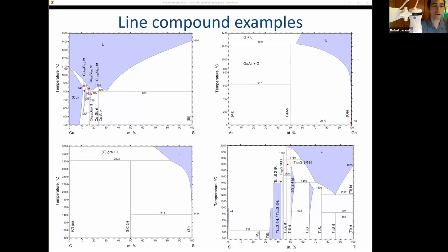Okay, so here's the copper silicon system. You can see that you can get a fair amount of silicon into copper, up to 10%. That's this purple region. There are silicon bronzes and silicon brasses, that is bronze and brass alloyed with silicon. Those are ternary systems, but silicon tends to be a pretty useful additive for copper-based alloys.